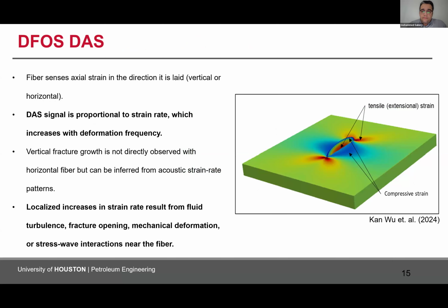For distributed fiber optic sensing data acquisition, we measure the acoustic signal, which is proportional to strain rate. That represents the deformation frequency in the rock.